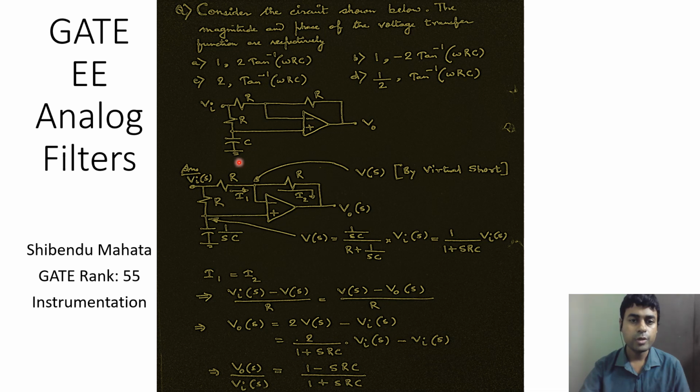With any op-amp based circuit where you have the presence of negative feedback, we have to target finding the voltage at either this node, the terminal connected to the inverting input, or this node, the connection to the non-inverting input terminal. Then we can use the concept of virtual short and claim that the voltages at the inverting and non-inverting input terminals are the same.